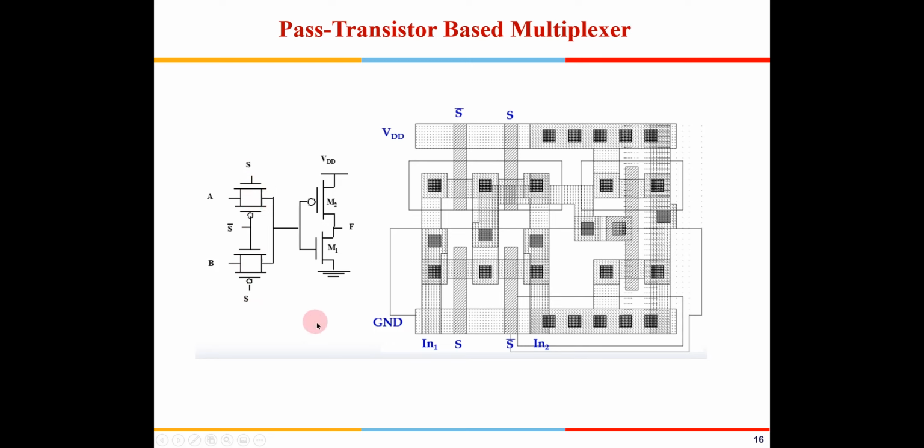You have 3 select lines and 8 input lines; those 3 select lines you give to a decoder and one of the outputs will be triggered on. So you can use a decoder and make a multiplexer, and a DMUX decoder generates the control signals.